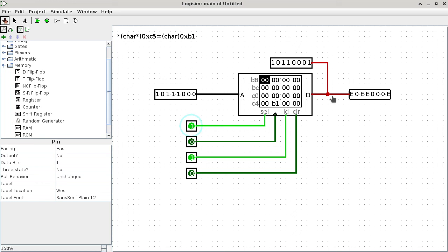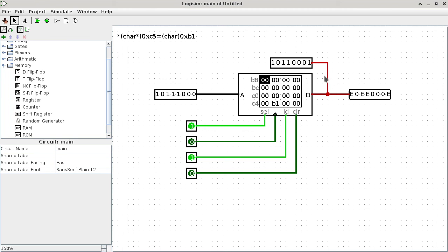Okay, and then somebody is going to say, oh, that's easy to fix, not a problem, because all we need to do is to disconnect the input pin, because the input pin serves no purpose when we are trying to read from memory. So you just go, okay, now everything is good again. But this requires me intervening and changing the circuit to get rid of the bus fight. When you're doing this inside the processor, you're not going to have someone from the outside to change the configuration or the wiring. So sometimes the wire is there and sometimes the wire is not there. So how are we going to fix this problem?